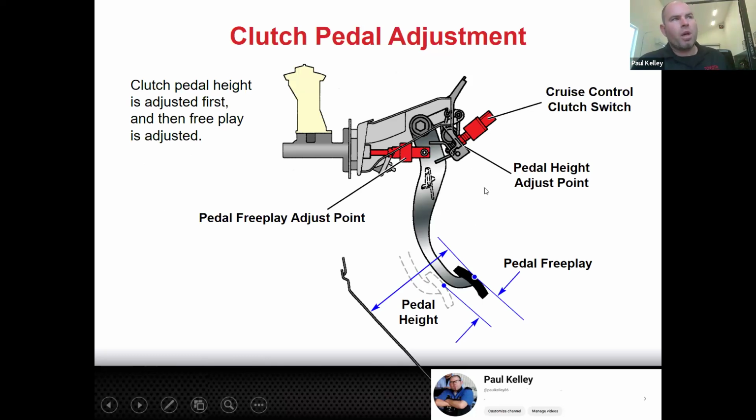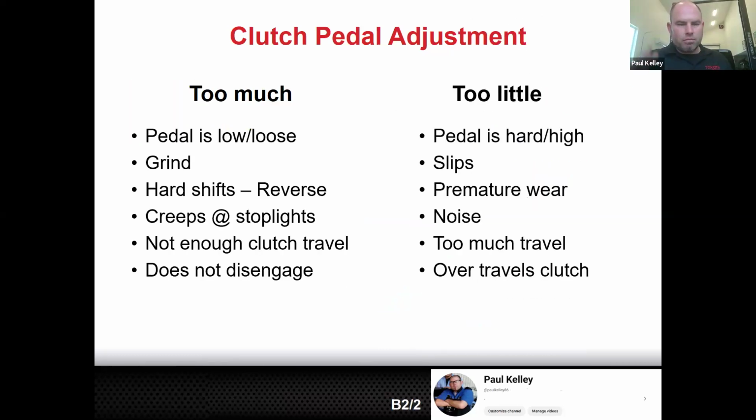It's going to try to shove your pedal up, but your pedal has a stopper. So rather than shove the pedal up, it actually starts to plunge this piston. And that starts to send fluid from this hydraulic master cylinder, pushes the fluid, pushes the slave, pushes the fork. Now your fork is actually pushing up against the release mechanism, the throwout bearing, the release bearing, right? That's why it would slip. Your pedal's up all the way, but the problem is your hydraulic fluid is still down a little bit, which is starting to release the clutch. And that's why on wide open throttle, it'd be slipping, right?